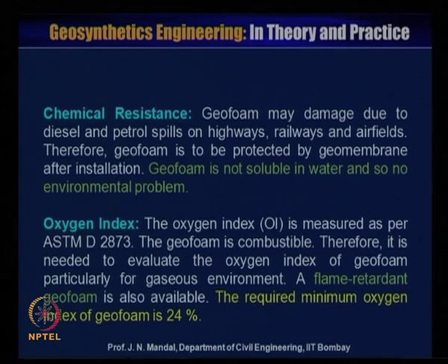So, it is always preferable that you provide the protection of a barrier or impermeable material like geomembrane, so that petrol and diesel cannot directly percolate through to the geofoam. That is the reason you should provide the geofoam material with the geomembrane as protection. Every material has its own advantages and disadvantages, but we have to observe overall how we can make use of that material safely.